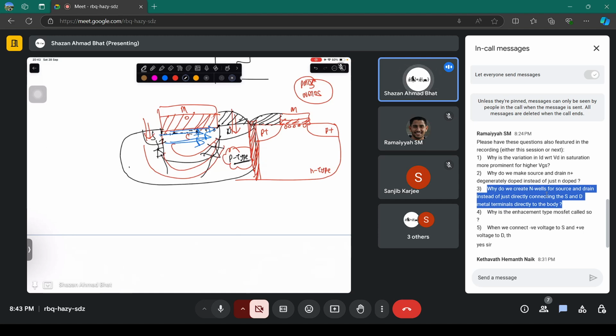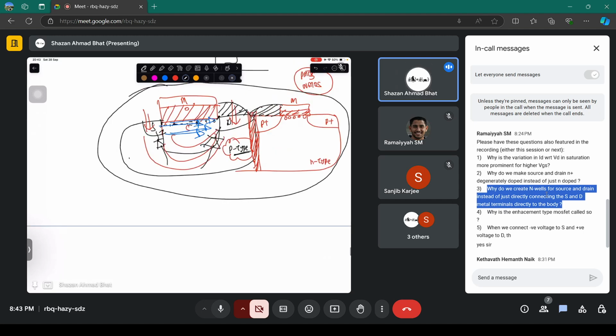You inject very high energy dopants into that region and dope it highly so that resistance in those regions falls. They almost become metallic, so conduction takes place only in those regions and you have good conduction. This is the overall schematic of a CMOS, where you have both P and N type semiconductor.